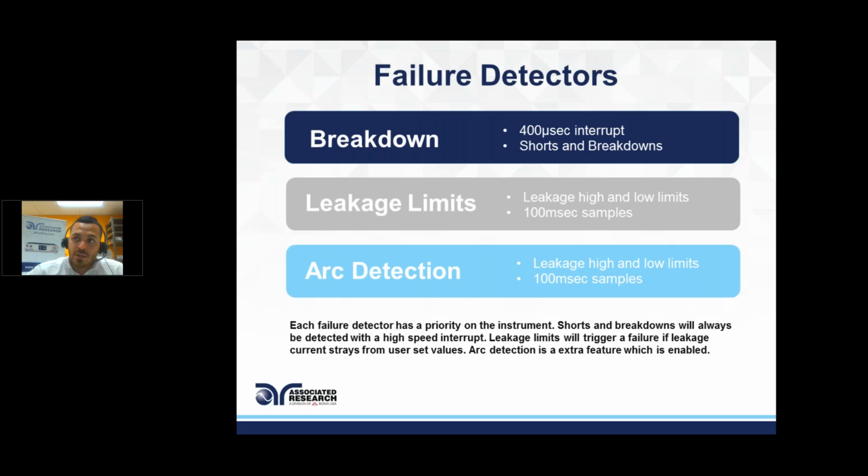So much current is now drawn by your product's insulation that the Hipot tester cannot supply anymore. You've now reached the power capacity of the transformer inside your Hipot tester to the point where it has to protect itself. I could probably output more current, but I might damage myself. So let me shut down and let the user know, hey, you just had a breakdown.